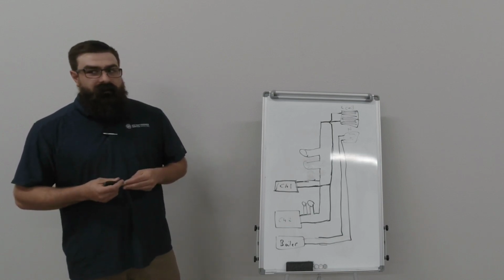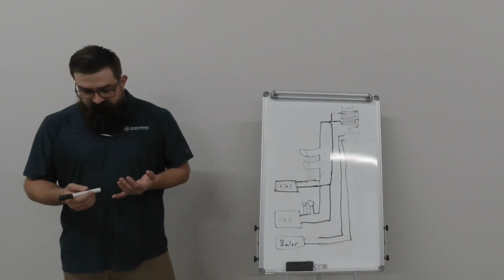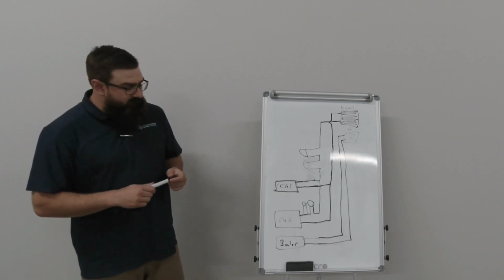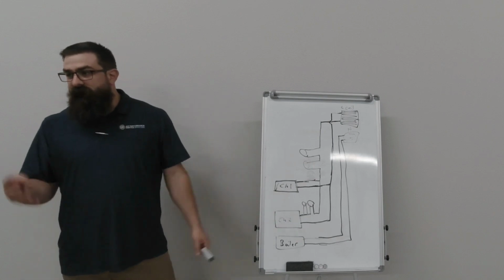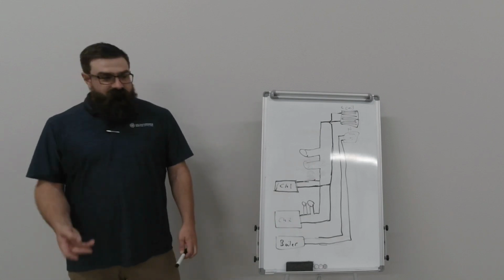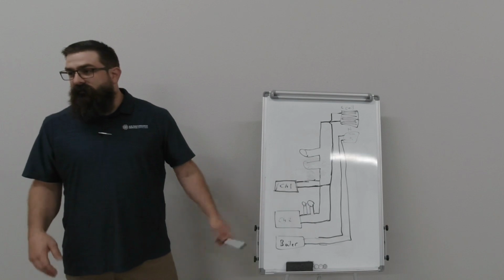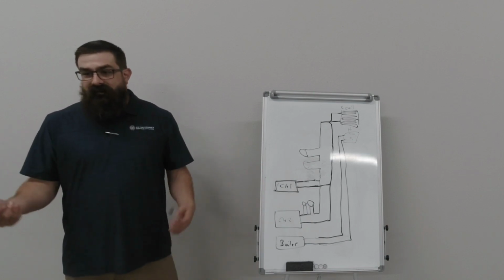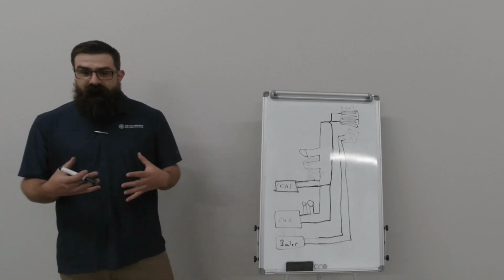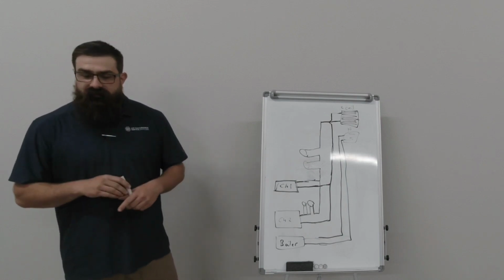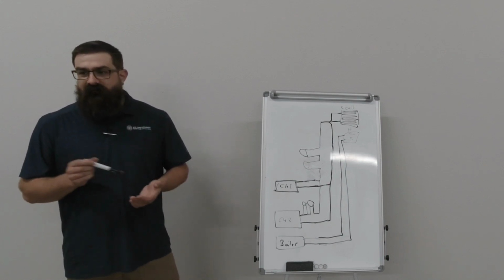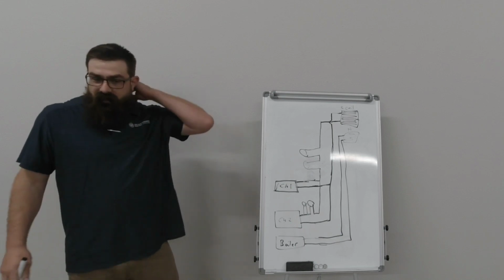common header. Yeah, I like common header because, as I was saying with the redundancy, if you were to do a dedicated with redundancy with 2 chillers, you now have 4 pumps, whereas if you do common with redundancy, you only have 2. So there's actually less involved on a common header until you start getting into valves and things like that. But typically nowadays they're putting valves on common and dedicated, so it really doesn't matter.